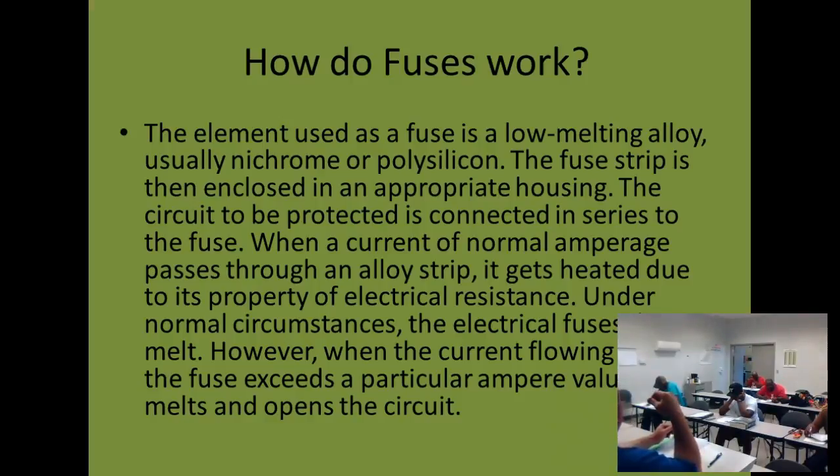But to start it, they're saying the locked rotor amps, remember, we call it locked rotor when the motor's sitting there not moving. When we start it, it has to start spinning. That's the hardest time. You have to have torque to get it moving. So they're saying that might be 150% as high. We may pull 50 LRA, or locked rotor amps, to get it moving.